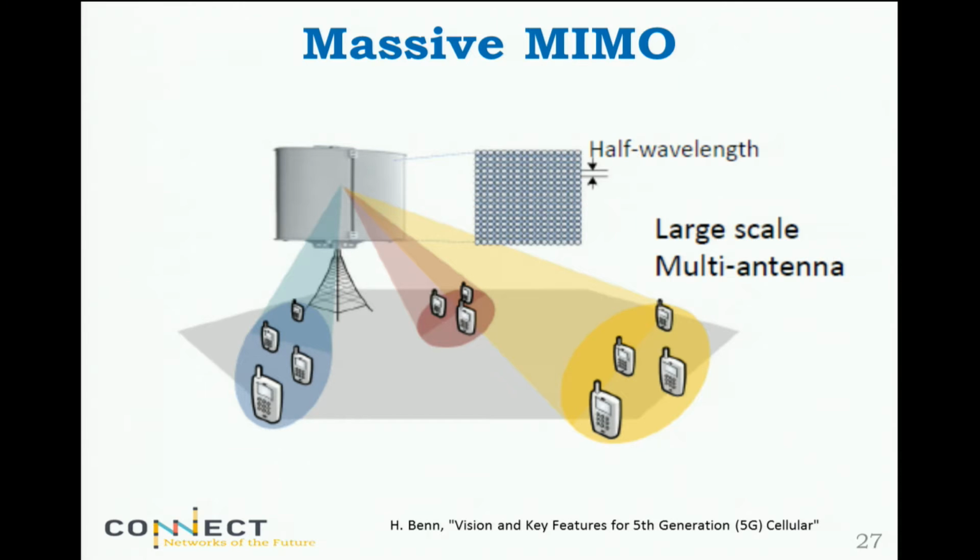Massive MIMO is really one of the giants in a sense in 5G. There is no talking about 5G without mentioning massive MIMO, so it is going to be there. It might be combined with millimeter wave because you can put the antennas closer together because of the higher frequency. Might not. Since you are not assuming multiple antennas at the mobile phones, only at the base station, you have the luxury in a sense to deploy a lot. Even at lower frequencies, say 2-3 gigahertz, probably not a big deal. Once you sort out the real estate problem, right, you have your own tower, then you can do whatever you want.